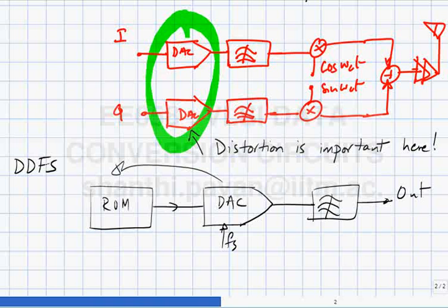and it gives you the opportunity to switch frequency on the fly without having to wait for oscillators to change the frequency of oscillation and all that, which takes a long time. This will give you instantaneous frequency hopping. A lot of communication standards have what is called frequency hop spread spectrum, where you keep changing the carrier at which you transmit, and it typically becomes very difficult to have a local oscillator which also follows those hops as quickly. A good solution in that case is this system, and today a lot of these function generators also exploit this principle.